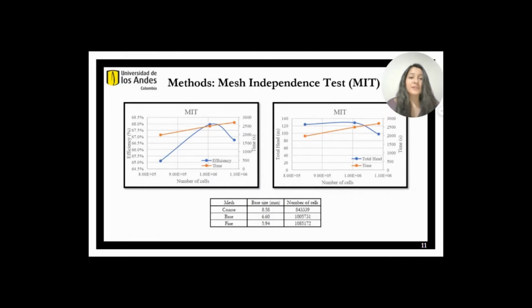To get an accurate mesh and solve the problem of the decreasing base size and the big changes between cells and prism layers, it's important to make a refinement in some special areas, and we need to add more prism layers. In the industry, it's recommended to use a number of prism layers between 6 and 10. So, if we use at least 6 prism layers, we may obtain an accurate mesh.